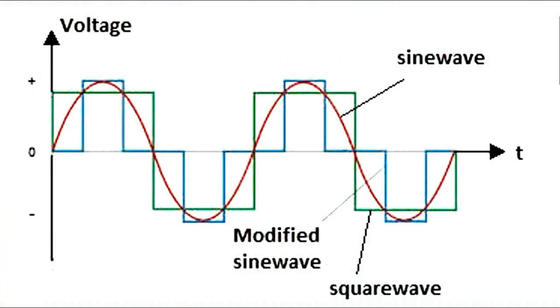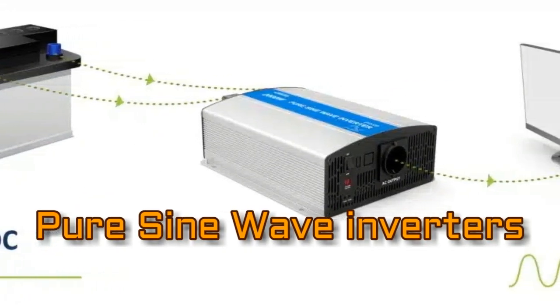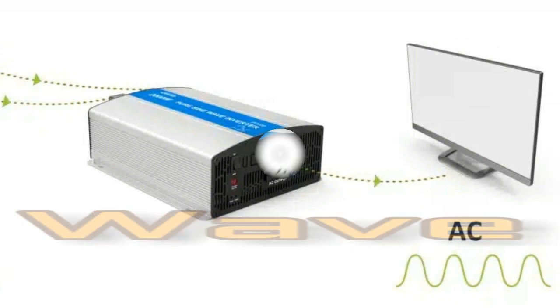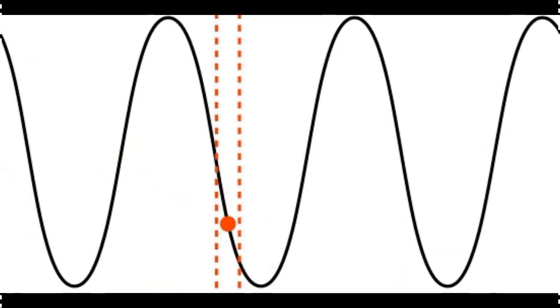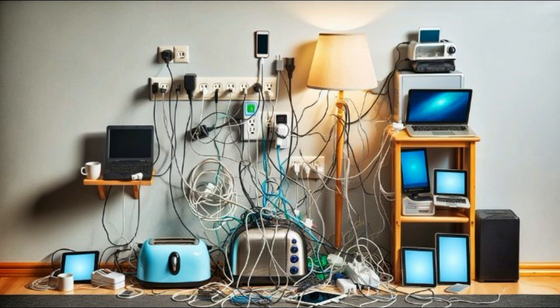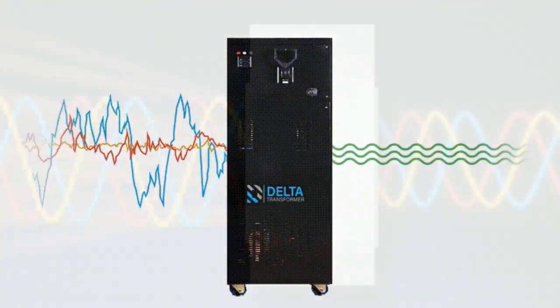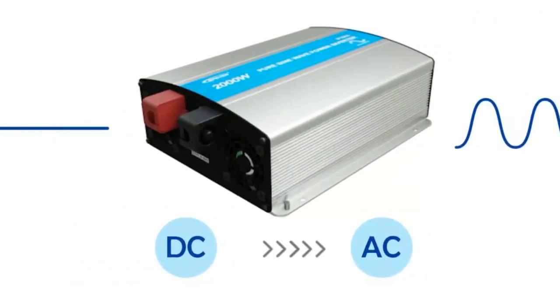You see, the red line is the pure sine wave, the green line is a square wave which is easy to create electronically, and the blue line is a modified square wave to make it more like a sine wave. While an inverter can produce different waveforms, a pure sine wave output is preferable because many electrical products are designed to work best with a sine wave AC power source. A high-quality and well-designed inverter ensures that the output is purely in the form of a sine wave with minimal conversion losses in the system components.